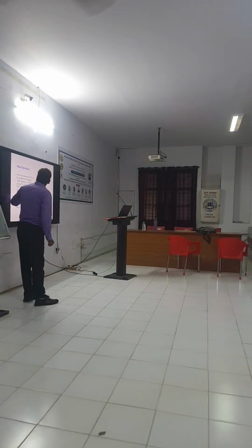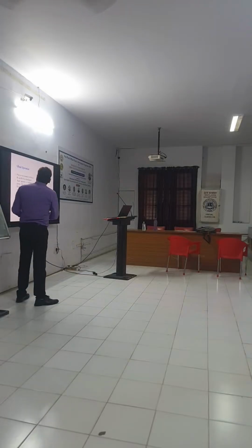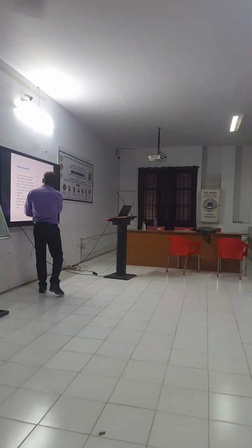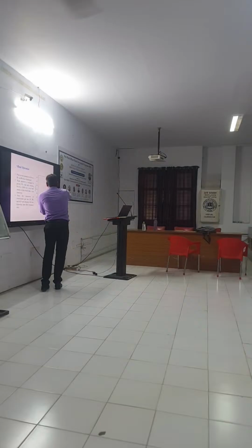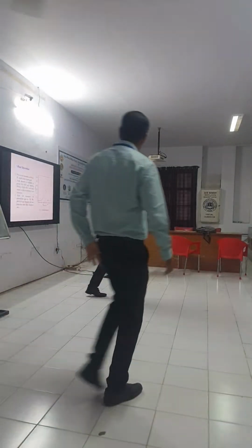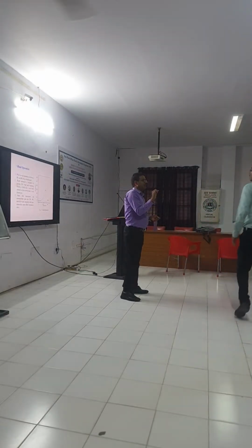The read operation is initiated by raising WL high, WL bar low. Once the transmission gates are on, BL and BL bar will charge. See, this is increasing, and this BL and BL bar are connected with a differential amplifier. I already talked about that.